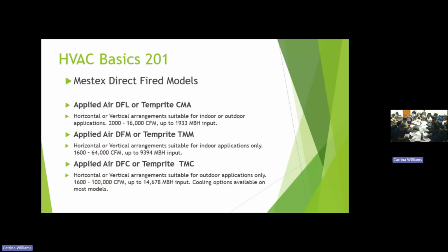They're never going to be allowed for 100% return air like a home furnace would be, but we can bring up to 80% return air, 20% outside air to help purge some of the combustions and still keep the building safe. And that is allowed by the new standards.